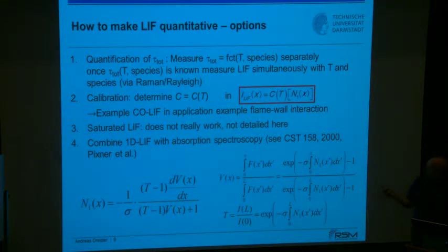So in the post-flame region, for example, that is a possibility by a simple extension: measuring the ingoing intensity and the outgoing intensity, to get an estimate of the concentration along that beam path. I refer to publications where that has been derived. So what are the important quantities? T stands here not for the temperature, but for the transmission, so this is the outgoing intensity over the ingoing intensity. Sigma, again, is the cross-section. And this quantity V over here is defined over there.